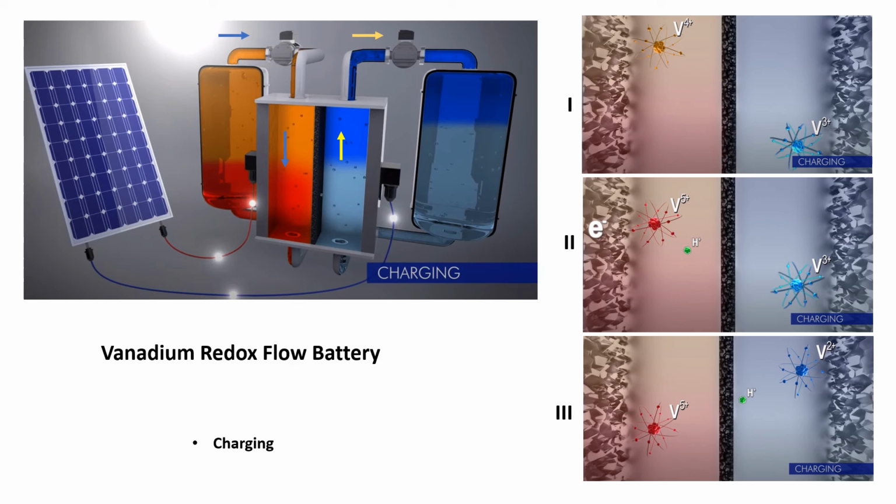The electrolytes are charged within the cell, and flow back to the tanks, which determines the storage of the charge. The cell chemistry involves redox reactions of vanadium. At the catholyte half cell, vanadium 4 is oxidized to vanadium 5. This yields an electron, which is driven to the external circuit, and the hydronium ion created simultaneously moves across the ion exchange membrane to enter the anolyte half cell.